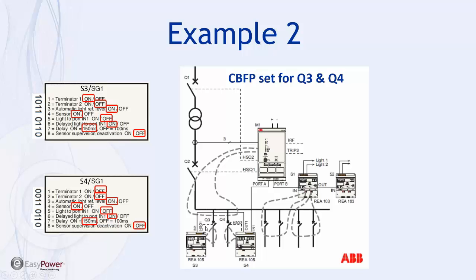And then for breaker failure, what we want to do is we have to have this light via input 1 to the main off. And then we can use breaker failure, so that's something to keep in mind. And then we can set this switch to on, which delays the light to the main unit after a pre-programmed delay. So if you have a breaker failure condition, then the delayed light signal will cause the main to trip Q2 to clear the fault. You don't have your selectivity. You also add a little bit of incident energy to the system.